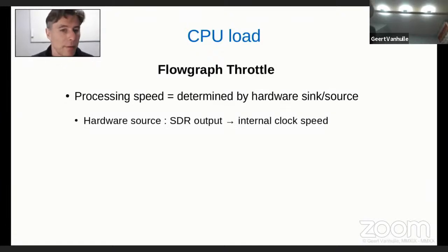Imagine what we can do in GNU Radio. We could have a virtual source, a sinusoidal signal generator that is completely producing a digital sample stream in the flow graph, so without coming from hardware, just mathematically calculated samples. And these samples go to a sound card, for example.